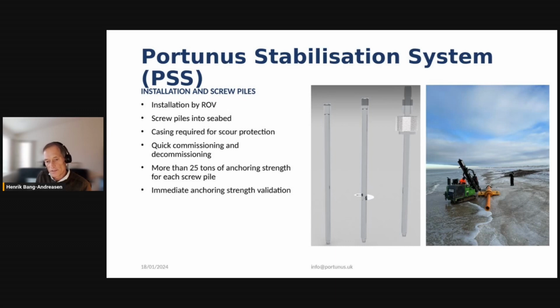We can achieve, or we will achieve, more than 25 tons of anchoring strength for each of the screw piles that we use, and also we get immediate anchoring strength validation. This we provide via a cloud-based system. So on board, in the vessel control room, one will have the data on the actual validated anchoring strength of the screw pile during the screw pile operation.